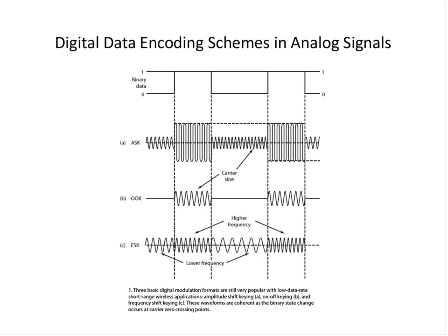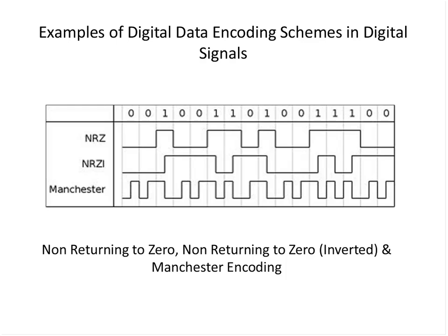The third one is frequency shift keying. These are ways in which you can put digital information into an analog way just by playing with the parameters of frequency and amplitude, and in this case, the carrier crushing it to 0 or letting it oscillate, whether it's a 0 or a 1. This is very important because there's so much stuff out there that's running this way. You have analog waves carrying digital information. Modems work like this.